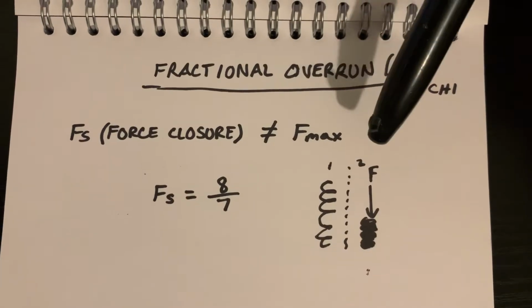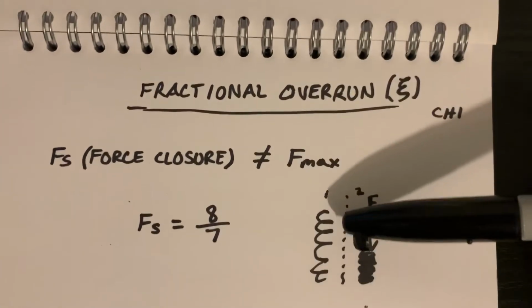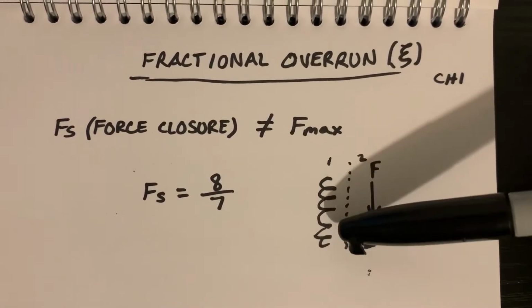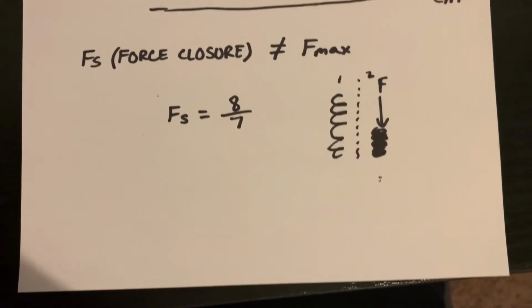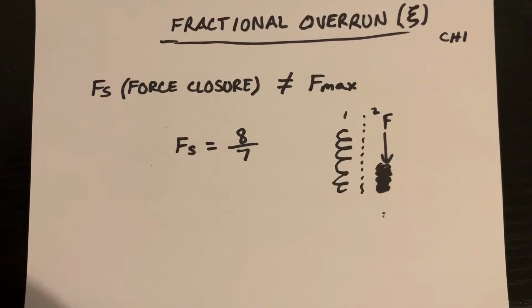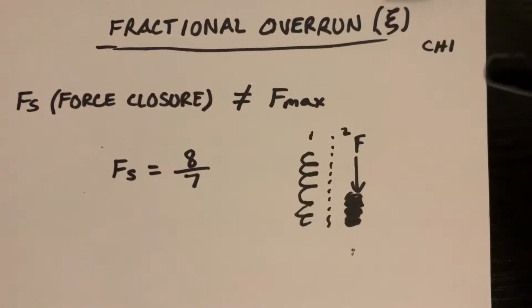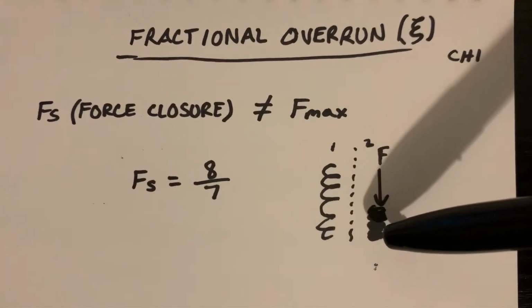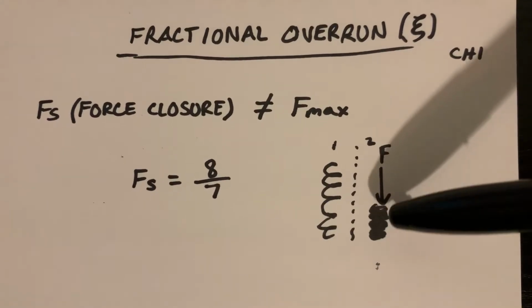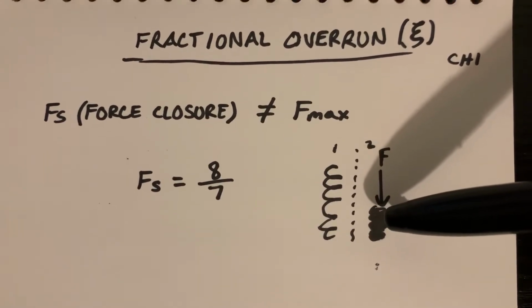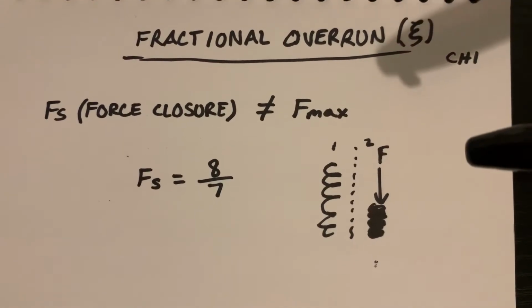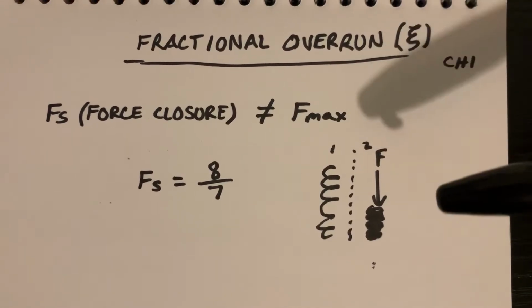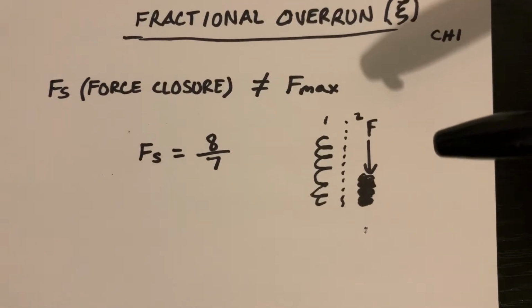That's because mostly a spring's force-deflection curve shows a linear profile. However, once it gets more and more compressed to where the coils start to touch, the number of active turns diminishes, and so more non-linear behavior occurs.